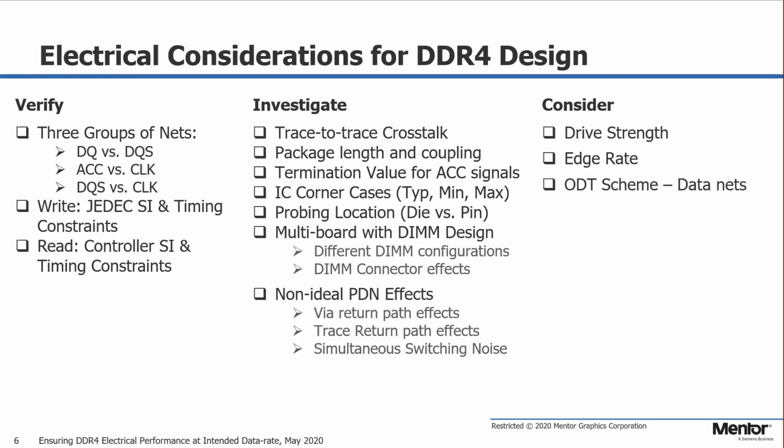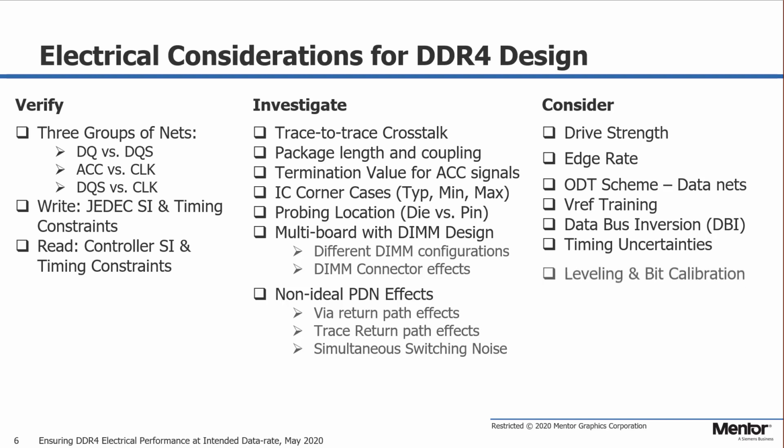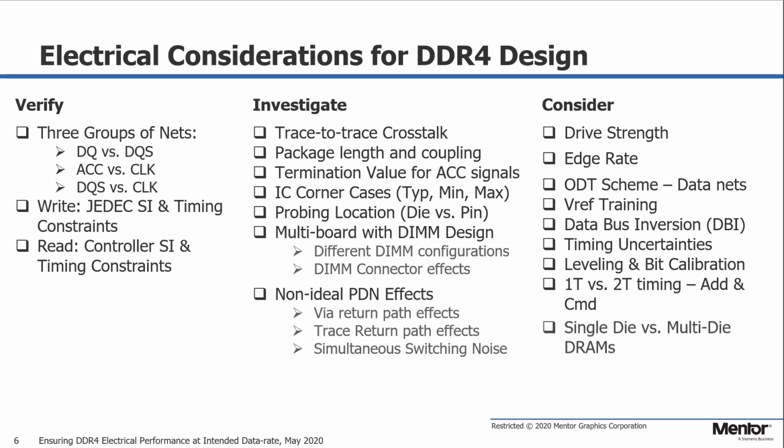I'll cover some background info on some of these items next in case you're not familiar with them. For example, I'll cover why the controller needs to perform VREF training and DBI and how they can affect your design margins. I'll also show in the demo how these factors can be varied or included in the post-layout verification process using HyperLynx.